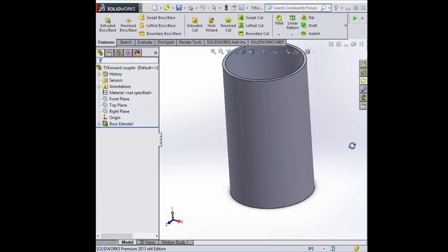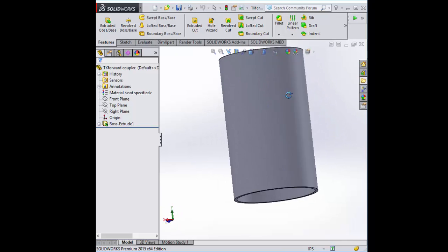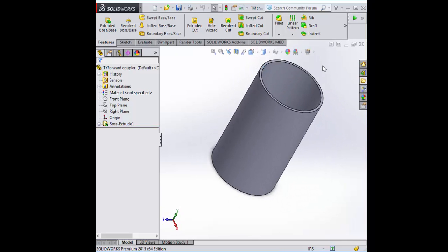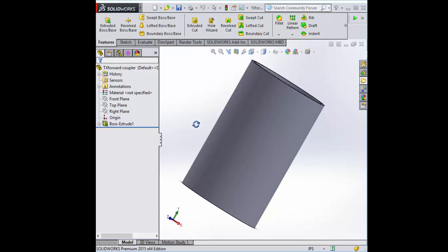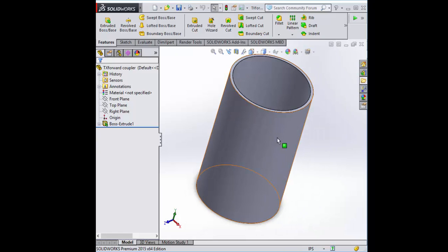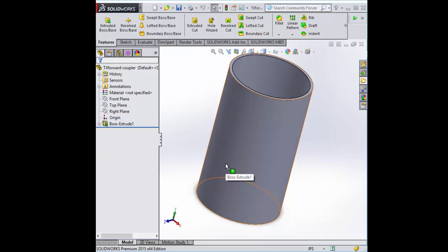Here it is. Here's our plain cylinder extrusion that we created a while ago. Now, according to the drawing, we want to add in another hole pattern. These will match the forward hole pattern on the payload tube that was also constructed earlier. So how do we edit it? It's just like you are opening up a new sketch. You just pick up where you left off and add in a new detail or new feature. In this case, it's a hole pattern.